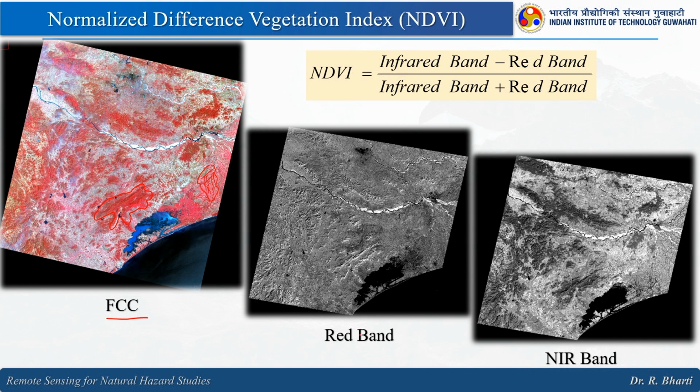When we consider the inputs, the infrared and the red band. So, here this is the infrared band and this is the red band. In the red band, if you remember the vegetation spectra, we have the absorption feature, right. So, the darker pixel here will be representing the vegetation, but some other target may also have the absorption feature here in the red, that is your water, right.